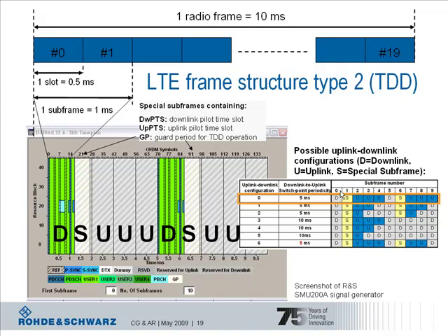Now the gray subframes which are indicated here in the screenshot are representing the uplink transmission. They are available for uplink transmission in this specific uplink downlink configuration 0. Also for TDD you have certain layer 1 and 2 downlink control channels defined at the beginning of each subframe, and you have also certain primary, secondary synchronization signals and a physical broadcast channel defined.